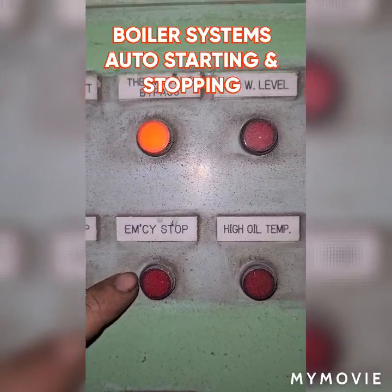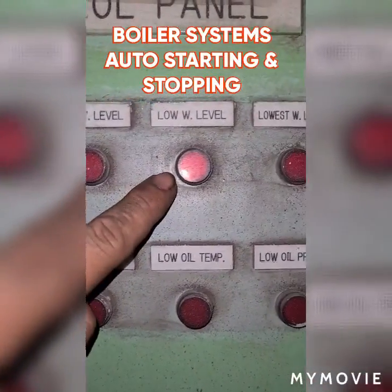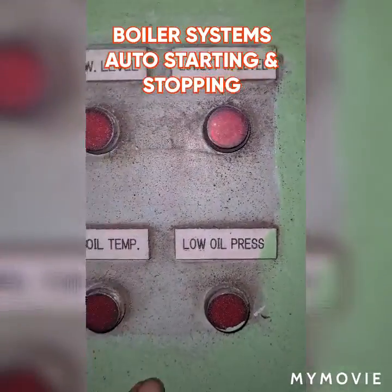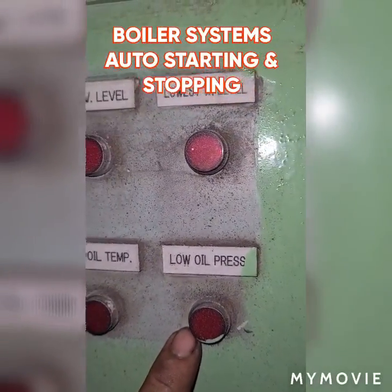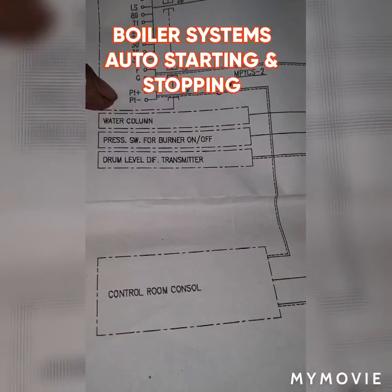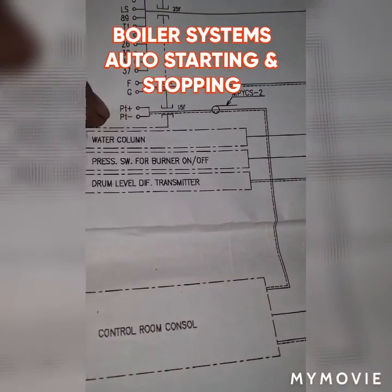This is my high water level alarm, and that is my high oil temperature alarm. This is my lower water level alarm. This is the low oil temperature alarm. This is the lowest water level alarm, and this is the lower oil pressure switch alarm, if the pressure drops from 2.2 to 1.86 megapascal. Here is the pressure transmitter from which the pressure indicator in the engine control room takes its signal.